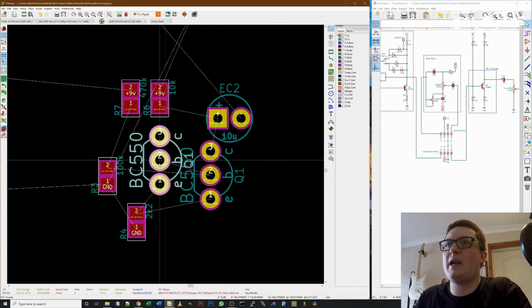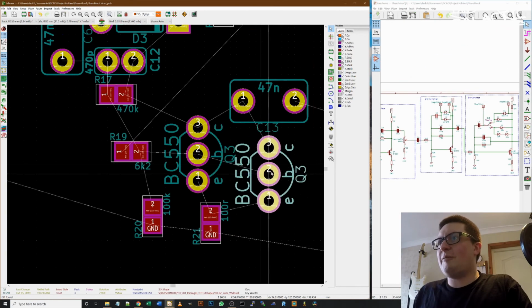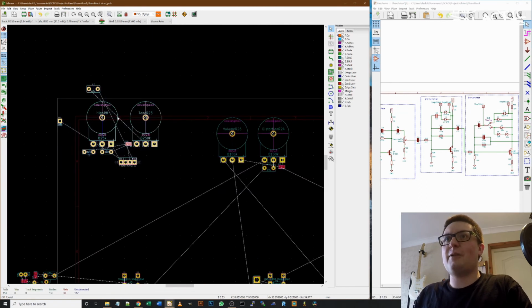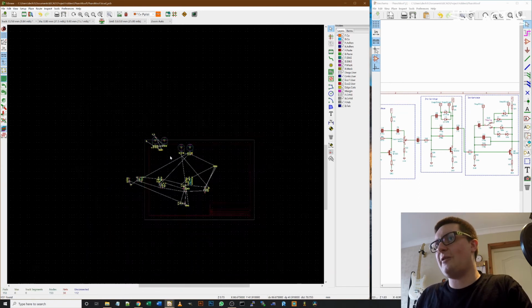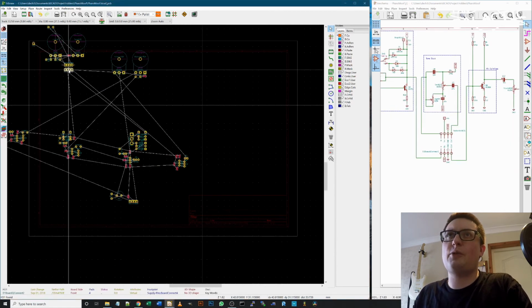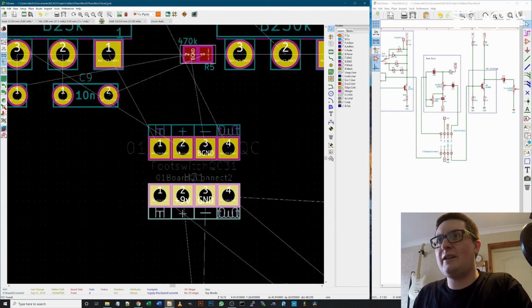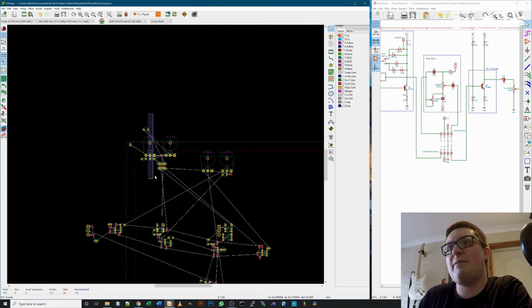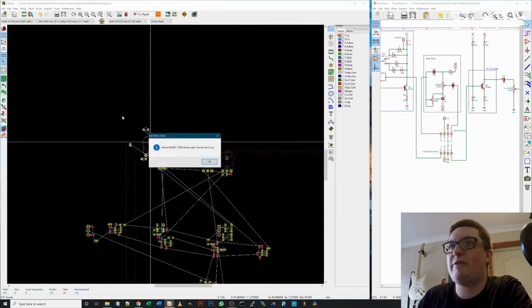Right, there we go. Okay, we're back to where we were. All these footprints now at least are correct. We just got to change them back to SMD, and we now have a completely separate daughter board with our tone stack on it. So the idea is we can put these two parts next to each other and do a board cutout, and now it should go in to in, plus to plus, negative to negative, and out to out. So if we join these two up, it will be in circuit, so we can now put a little header pin in here, and we may even be able to, if we're clever, make a little plug-in tone section, which then means we can later copy this board and just do different versions of this.